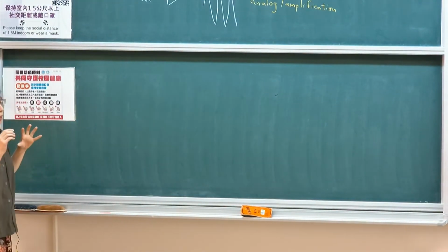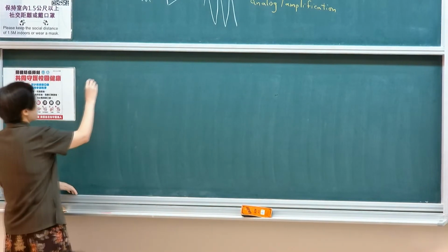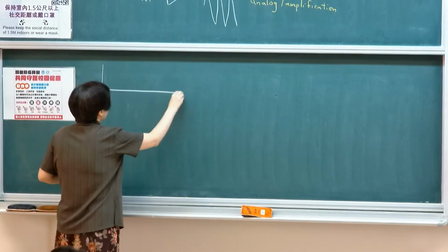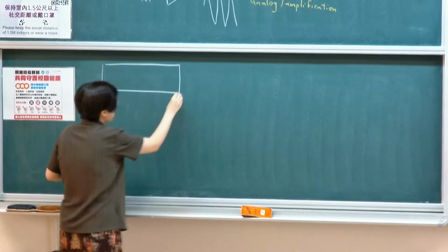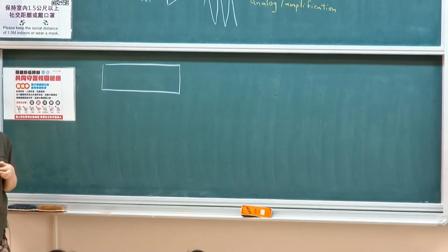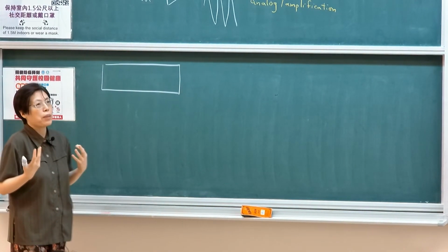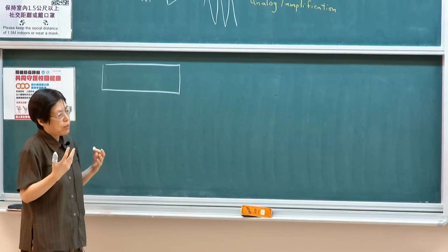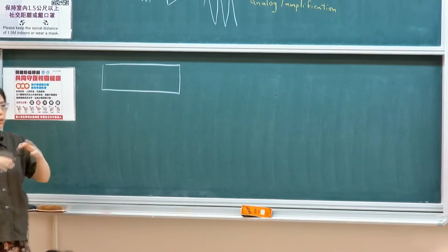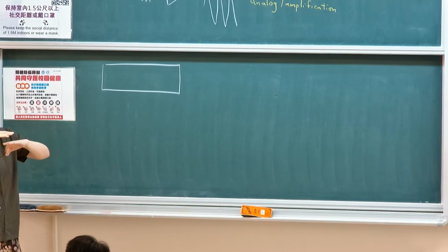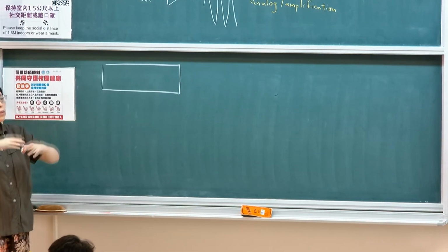So we're going to go back to the structure a little bit. Remember, we already talked about this. Some of the students asked me why, when I talk about device structures, I put the emitter on top. The reason is that for the NPN transistor, this is how you build it: your emitter will be at the top of the surface, close to the surface.